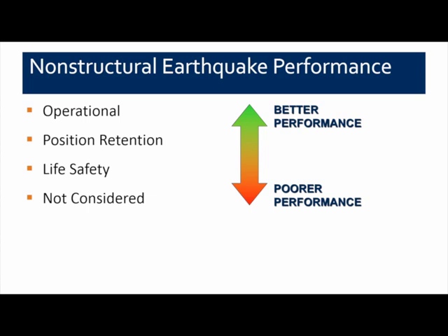And then the next level of performance is what we call position retention. In this case, we want the items to stay in place during the earthquake, not fall down and hurt anybody. But in position retention, we're not guaranteeing that those pieces of equipment may necessarily function following the earthquake. For life safety, it's basically a subset of non-structural components that are critical to affecting the safety of the occupants.